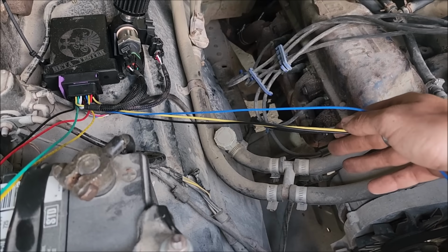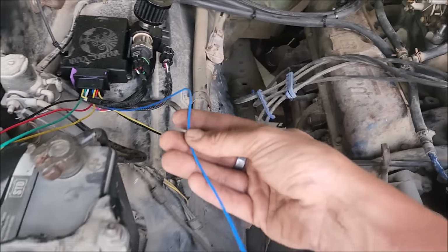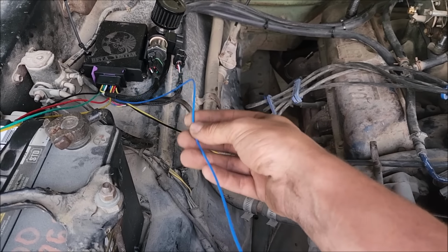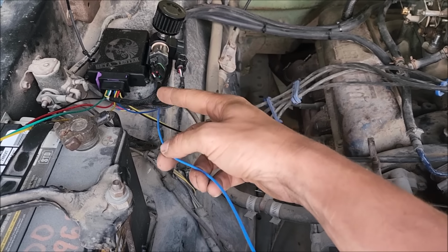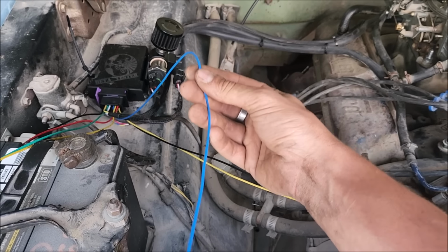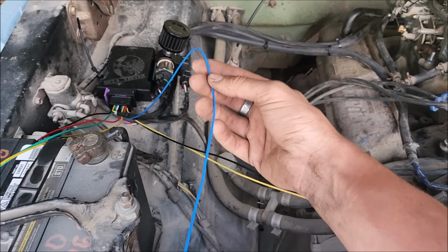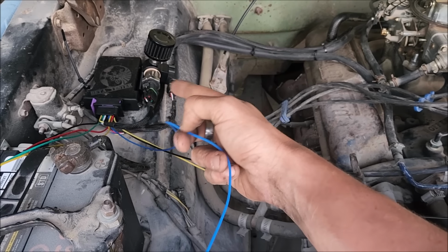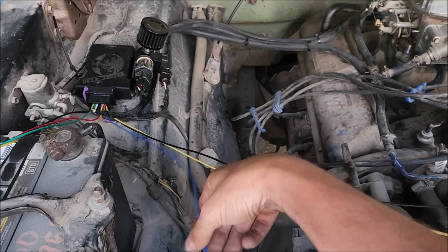Now these wires you don't necessarily need. This is if you have an auxiliary wideband, you already have a wideband, you don't need one from the kit. This is where you tag into the analog signal from your wideband gauge you already have. So Carb Cheater can accommodate an existing wideband, or we have our own on board that you can use.